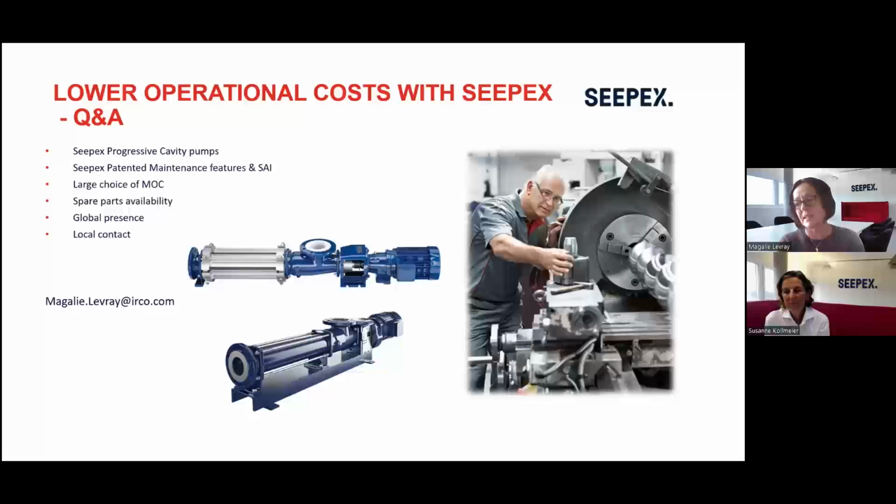The peristaltic pumps indeed are used, especially when we have some chemicals. However, the disadvantage is that the mining industry works 24/7, so the wearing of hoses can be quite frequent due to the rollers, and that will wear out the hoses, probably more sometimes than the fluid itself, but just the functioning principle will wear out the hose very fast.